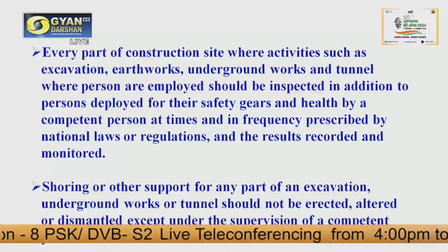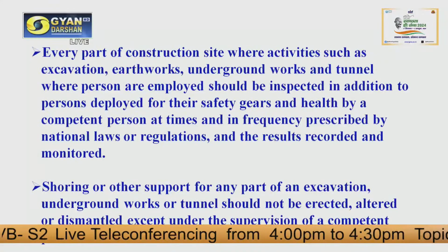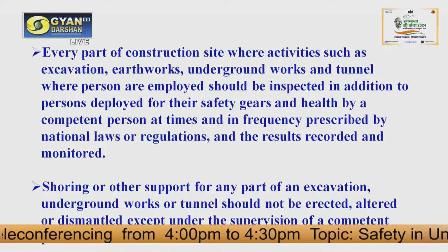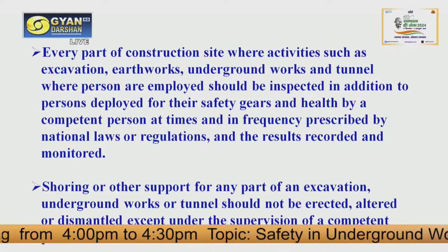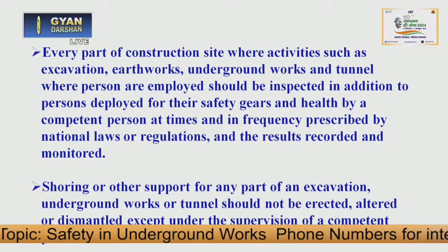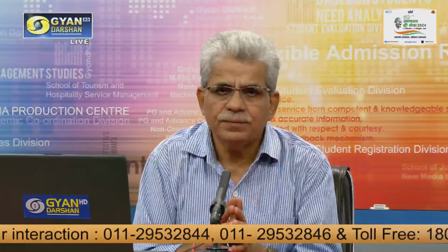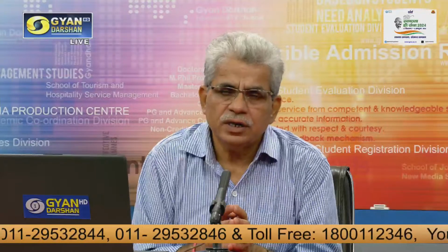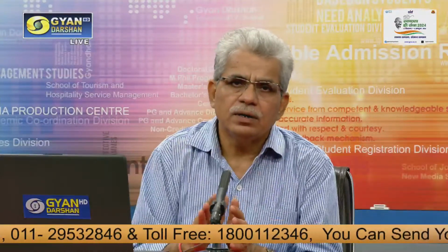Then, what we can do more is that shoring or other support for any part of an excavation, underground work or tunnel should not be erected, altered or dismantled except under the supervision of the competent person. There should not be any disturbance to the shoring and other support provided in that excavation area without the prior approval of the supervisor.